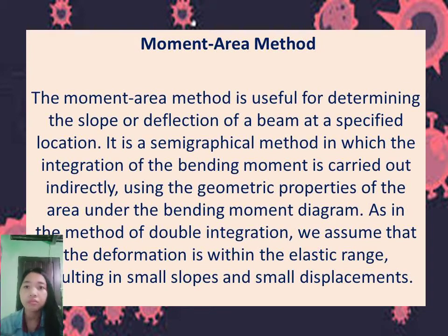So, the moment area method is one of the most effective methods for obtaining the bending displacement in beams and frames. In this method, the area of the bending moment diagrams is utilized for computing the slope or the deflection on the particular points along the axis of the beam or frame.